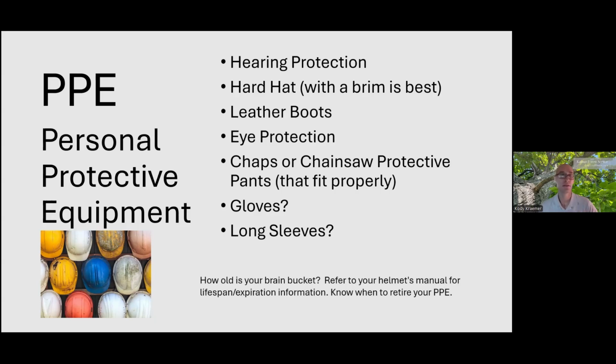And then talking about hard hats, having a brim is the best policy in case the worst were to happen and you experience kickback. That brim's going to protect your face. But I also don't want to see somebody wearing a hard hat that's 15, 20 years old. We don't often talk about it, but think about how old your hard hat is. There are expirations that go with all of these pieces of PPE. So know when to retire your PPE.